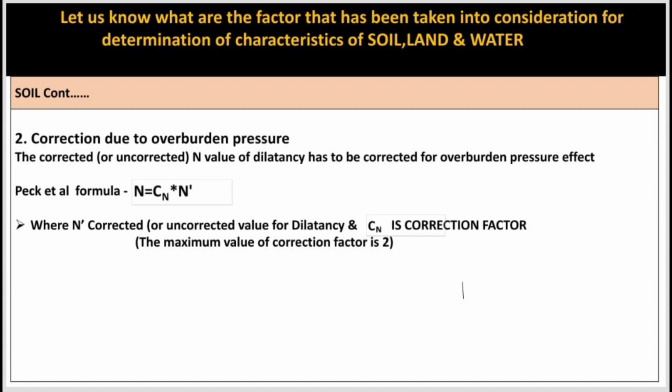What I observed is that in most cases we never go through the soil report. The nature of soil strata and soil characteristics is one of the most important factors. Most of the soil reports are submitted without the corrected value of N. Especially in the case of a river area, the correction is very important. Again, knowing the soil strata, we can plan properly. So, it is important to go through the soil report submitted by the contractor and the formula used by them.